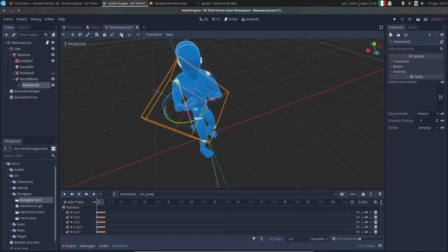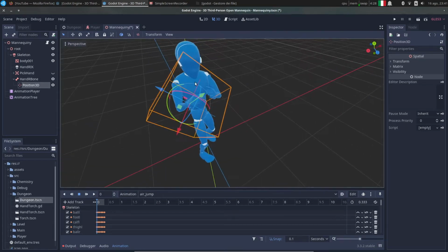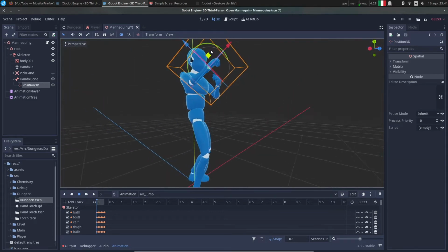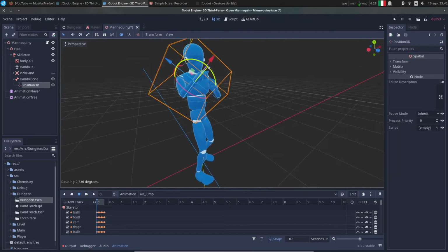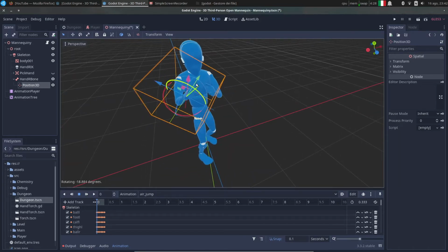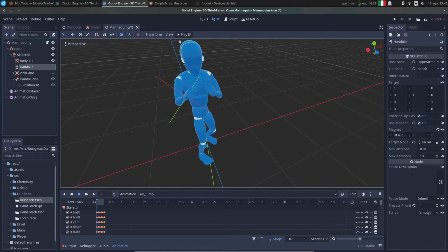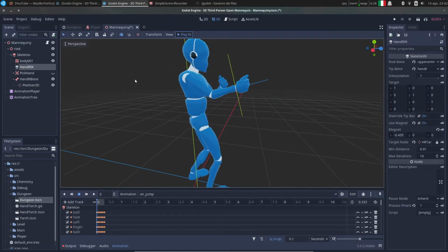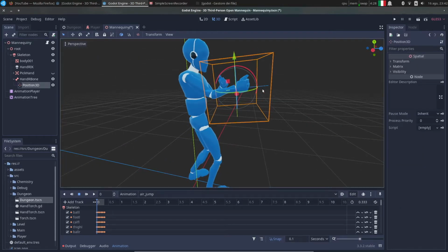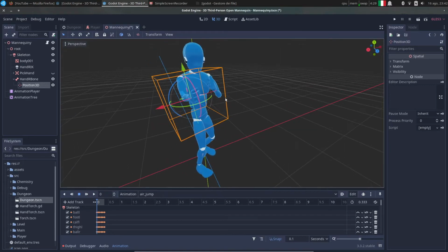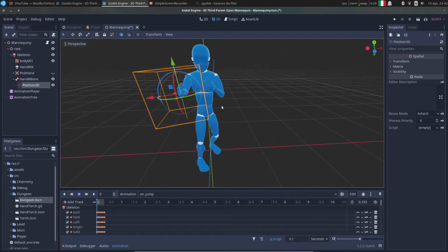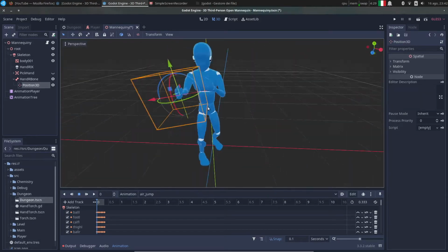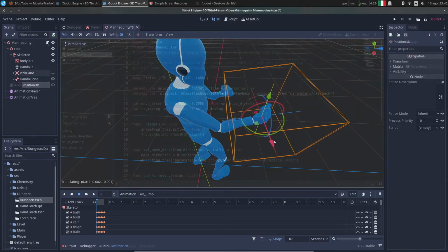The best approach is to enable use local space and rotate and translate the position node so that the gizmo arrows are pointing the right, up and front directions. In previous tutorial, I used the IK target directly to attach the picked object at the hand position. But that's not optimal, because bone attachment will always stay in the same position of the hand, making it optimal for the object to follow.